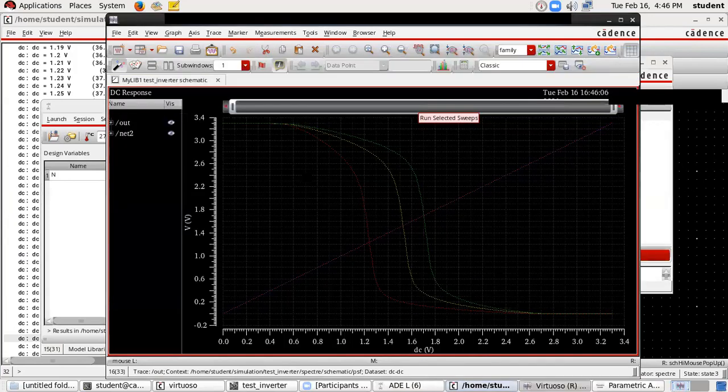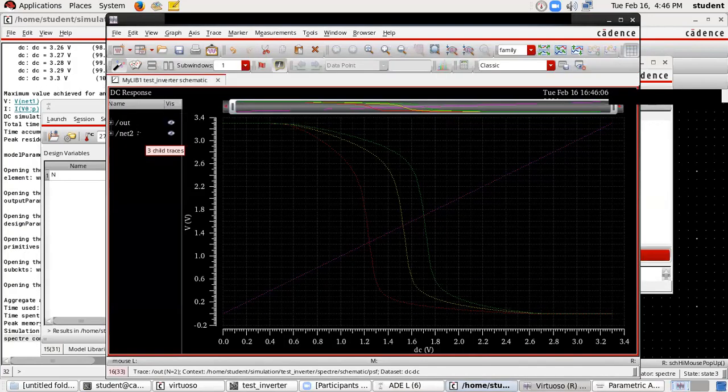you can see how the characteristics shift. They shift towards the right side, or the higher voltage side. It is obvious, right? If the PMOS width is going to be large, it is going to produce more current and it is going to dominate. And for PMOS, we know the threshold voltage is going to be on the higher side. So therefore, the characteristic itself shifts to the higher side. That is as straightforward as that.